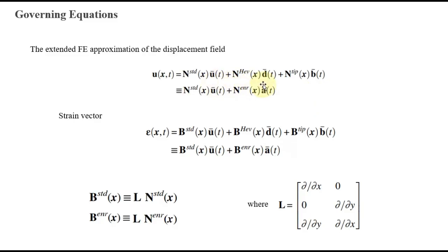The second uses the Heaviside jump function for modeling displacement discontinuities across cracks, and the third uses asymptotic crack tip functions to model singularities near crack tips. Accordingly, the strain vector corresponds to the approximate displacement field.